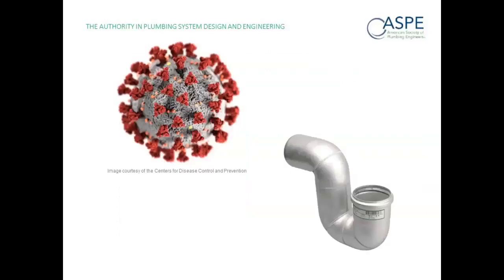All right, so now it's time to talk about the combination of plumbing and disease. So obviously we can't have this discussion without discussing COVID at this point. So research has demonstrated that there are certain strains of bacteria that will colonize microbial biofilm communities in a sink P-trap or drain. Usually they're antibiotic-resistant organisms, and they do not appear to amplify unless they are supplemented with liquid waste containing microbial nutrients. These can include soft drink products, intravenous fluids, or nutritional shakes. So as I had mentioned earlier in Scott's slide, we were talking about the necessity of providing nutrition in order for these things to propagate.